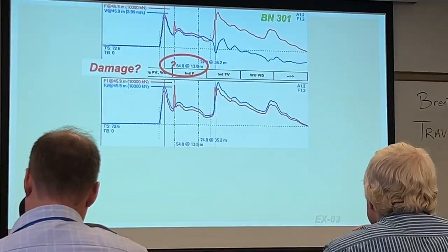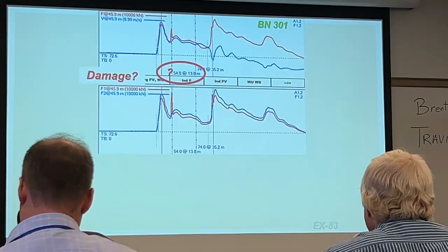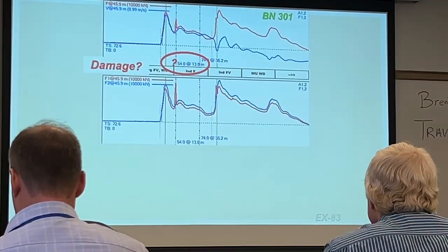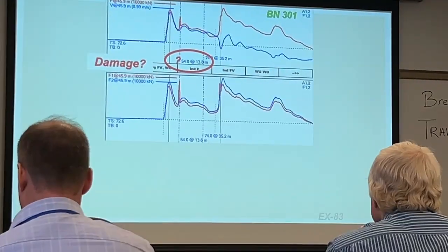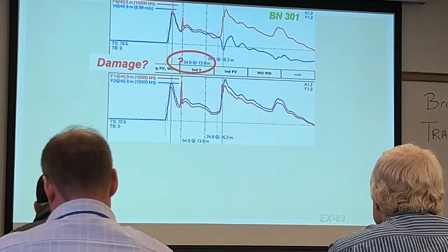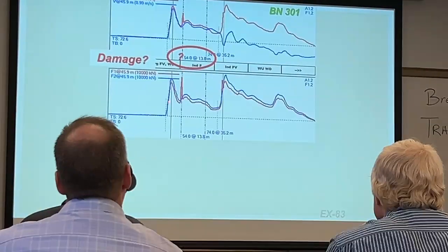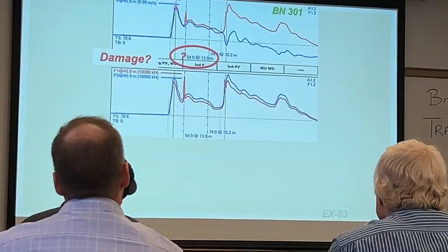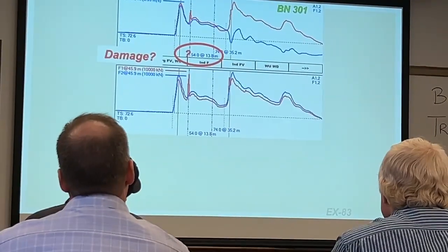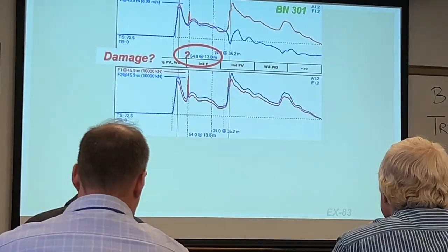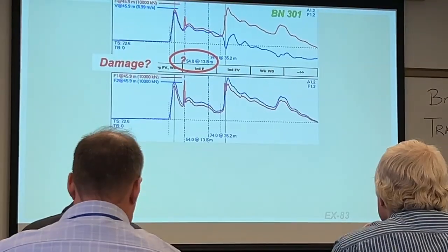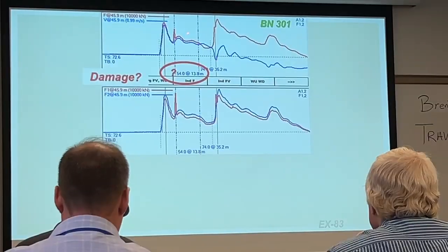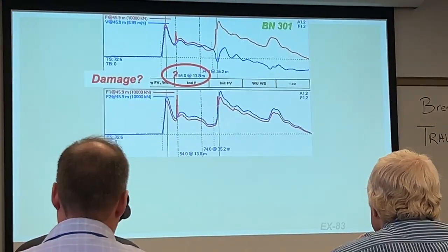And those types of sharp spikes are not usually indicators of resistance. Resistance is smooth. And so when we look at our individual sensors, we don't see the spike in F2, but we do see it very sharply in F1. And so again, that's a scenario where you want to ask about what's going on with this data set. So this is a problem with a wire in all likelihood.